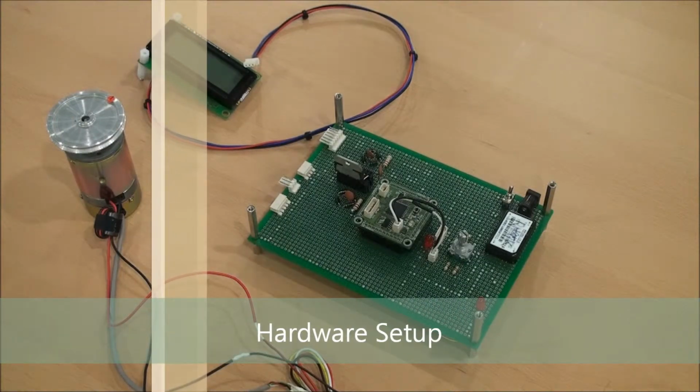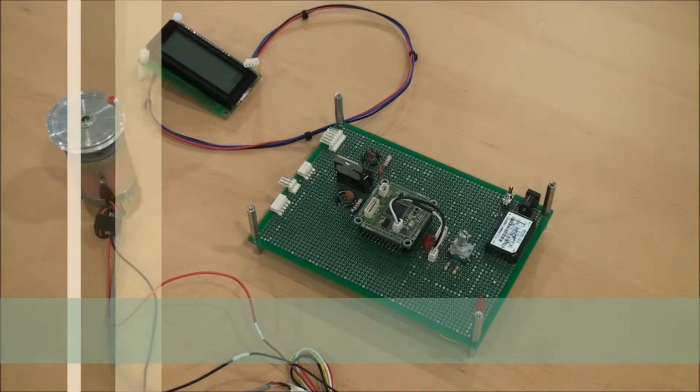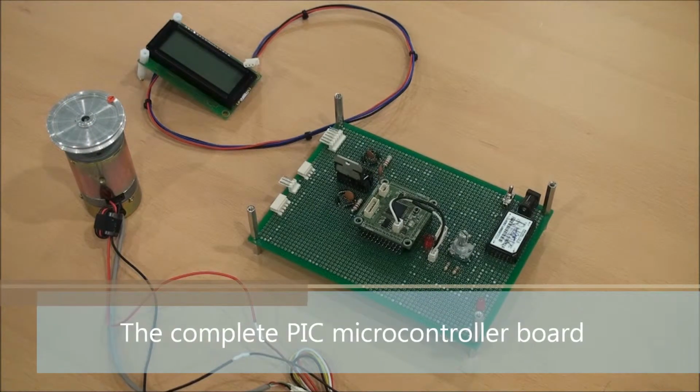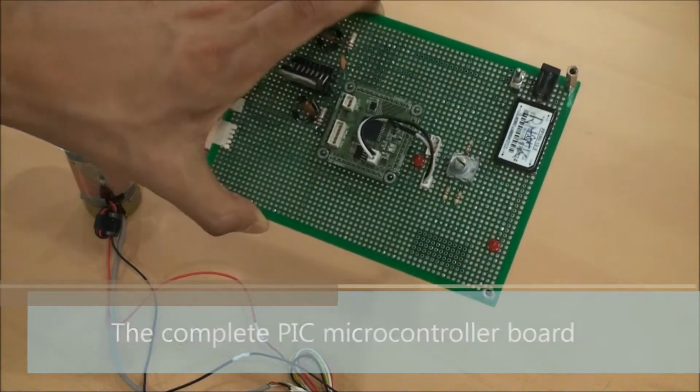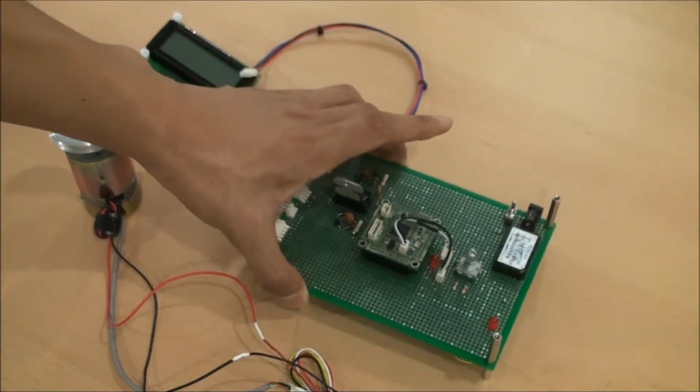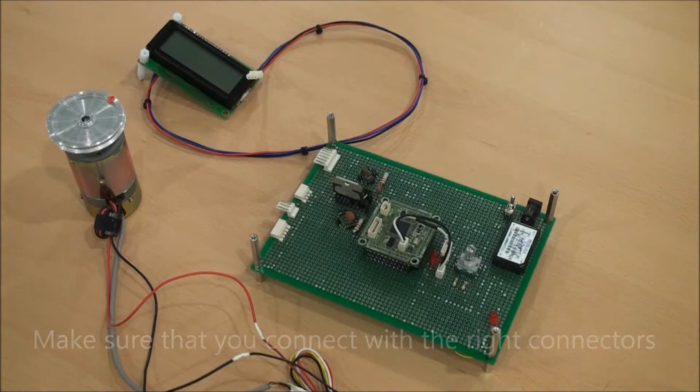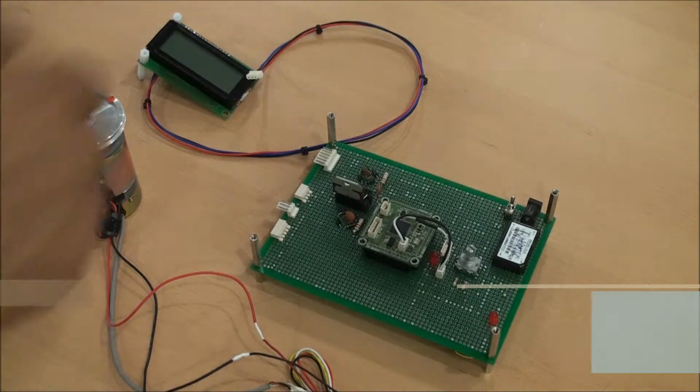Now, let's set up the hardware first. If you successfully completed the previous tutorial, you will have the PIC microcontroller board like this. The arrangement of your board could be different from mine, so make sure that you connect the LCD and motor with the right connector. First, connect the 12 volt power supply.